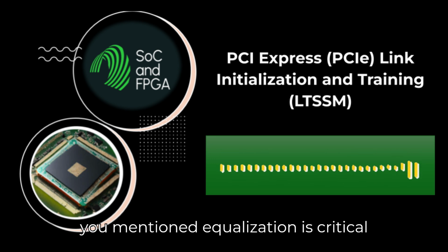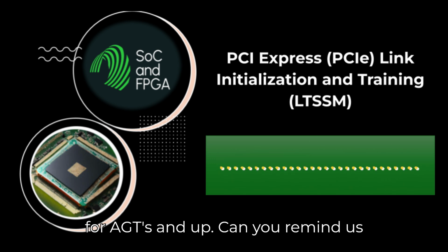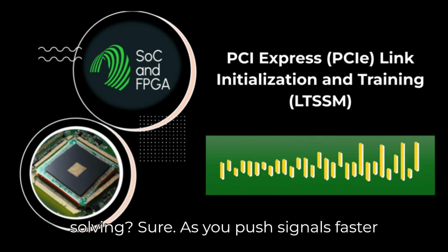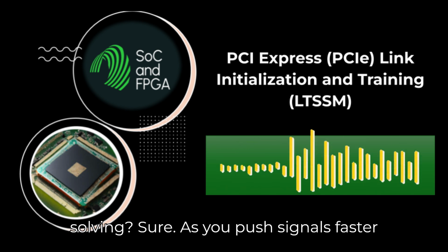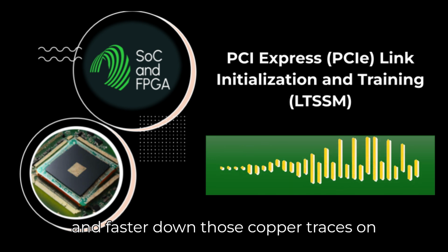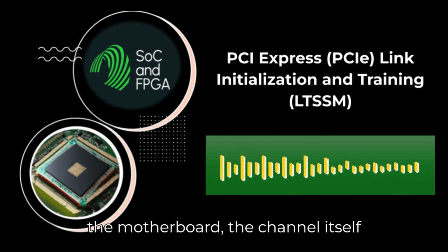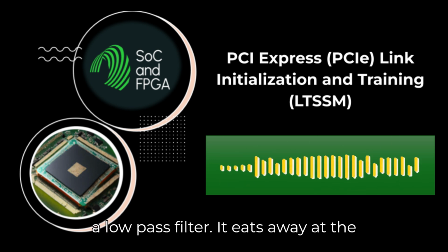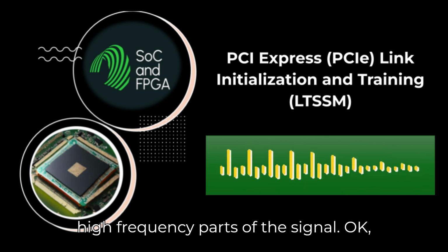Okay, you mentioned equalization is critical for 8 GT/s and up. Can you remind us why it's needed? What problem is it solving? Sure. As you push signals faster and faster down those copper traces on the motherboard, the channel itself starts acting like a filter, specifically a low-pass filter. It eats away at the high-frequency parts of the signal.